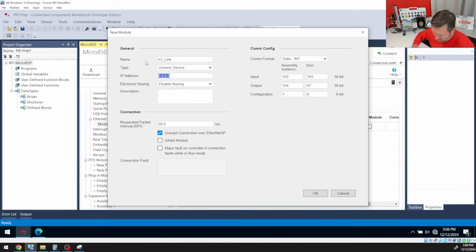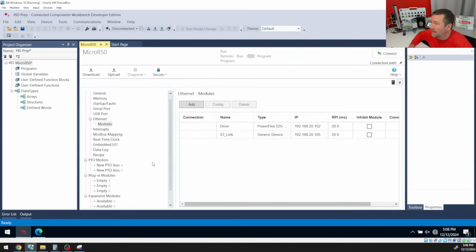I didn't enter the IP address. That is, for your trainer, it's going to be 192.168.1.15. The Micro820 trainer in the training center is 20.105. So I'm going to click OK on that. And then now, as I was going to say, we have a lot more to do, but let's download this and just talk about a few issues that you could have and how to see them and catch them before we're staring at data trying to figure out why it's not working. So I'm going to go ahead and download this program.